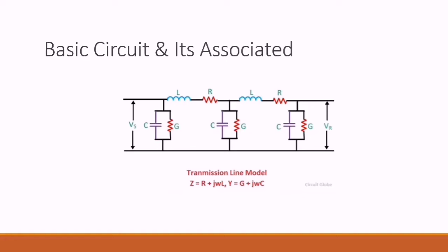Then we see the shunt impedance that consists of conductance and capacitance. When the alternating voltage is applied to the conductor, not all the current can flow because the dielectric is not perfect. The excess current can be labeled as leakage current because of atmospheric conditions and pollution like moisture.